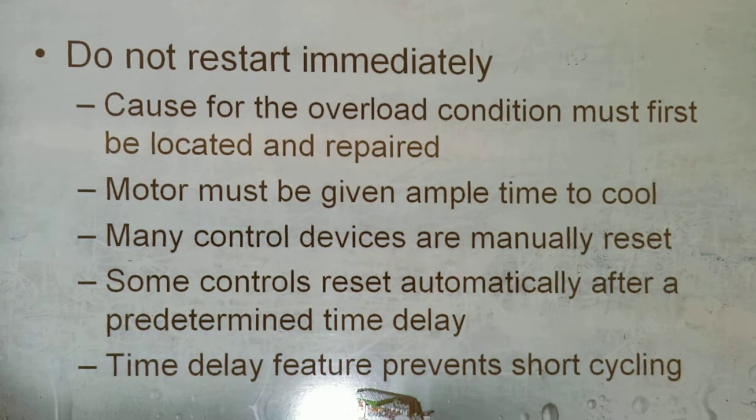Okay, so it says do not restart that motor if you see it go off. Depending on how big it is, you could do some damage. Any motor you turn off and on, turn on again, turn off, turn on, it's gonna murder that motor.